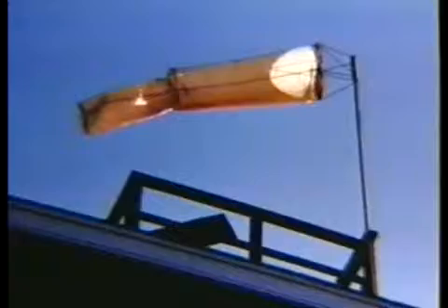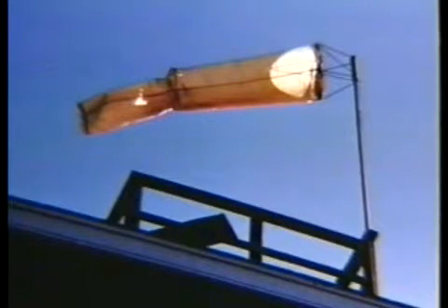Now, we've said that if the manufacturer's recommended final approach speed is not available, use 1.3 VSO. We can think of only 3 instances where this rule is not valid. So before going on, let me tell you what they are. The first is when you're flying a twin. Then you should be at the manufacturer's recommended final approach speed, or if you don't have that speed available, VYSE, the best single-engine rate of climb airspeed, a value which may be greater than 1.3 VSO. The second is when strong, gusting winds are present.